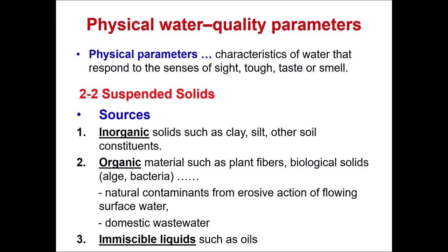Suspended solids are commonly found in surface water. So surface water usually contains significant amount of suspended solids, and the main source of these solids is surface runoff. Water flows over the land surface and carries with it various pollutants, including soil particles, organic matters, and other contaminants. As a result, suspended solid concentration in surface water tend to increase, especially after rainfall events.